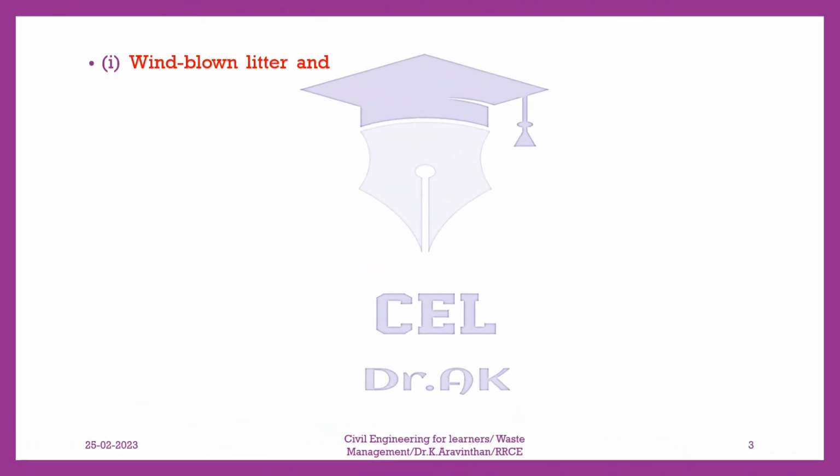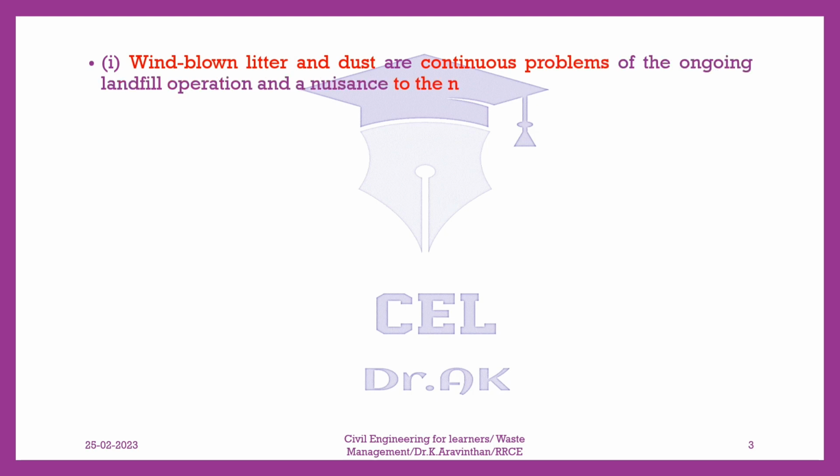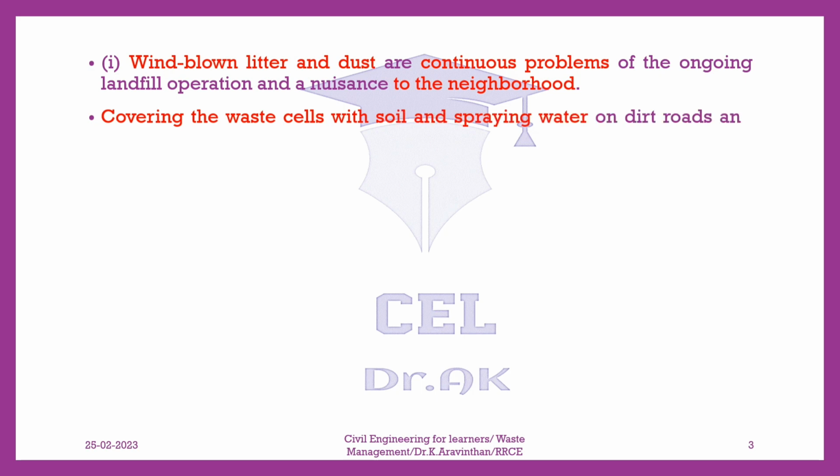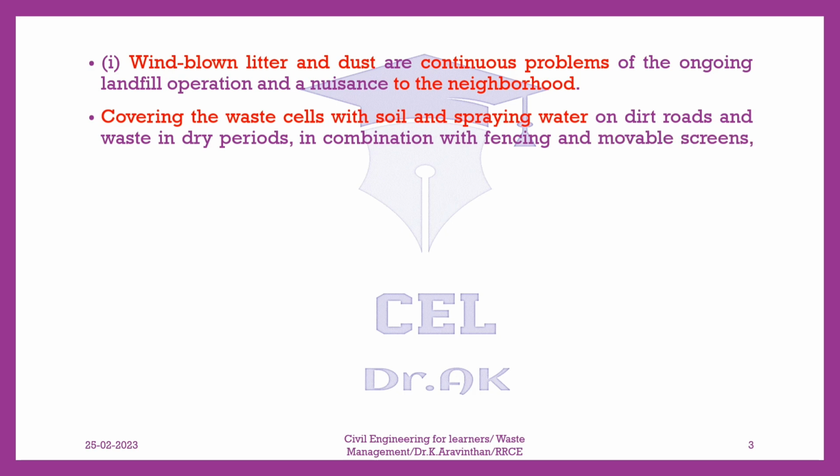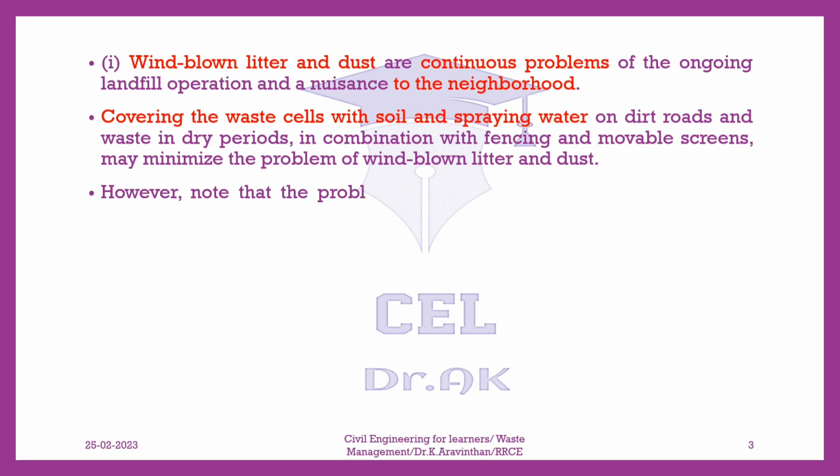1. Wind-blown litter and dust are continuous problems of the ongoing landfill operation and a nuisance to the neighborhood. Covering the waste cells with soil and spraying water on dirt roads and waste in dry periods, in combination with fencing and movable screens, may minimize the problem of wind-blown litter and dust. However, note that the problem will remain at the tipping front of the landfill.